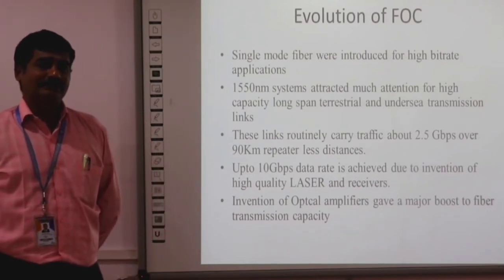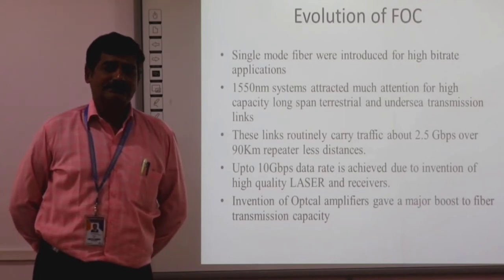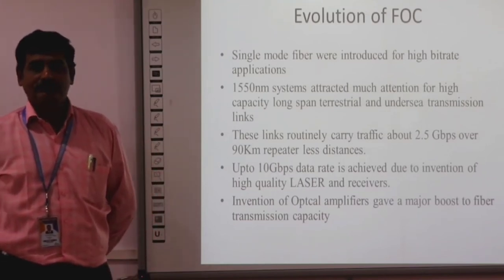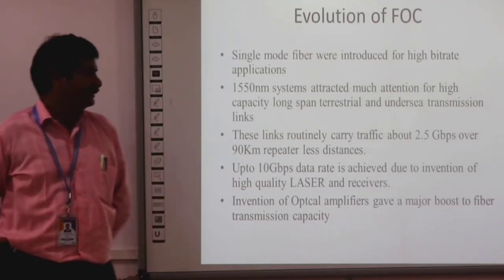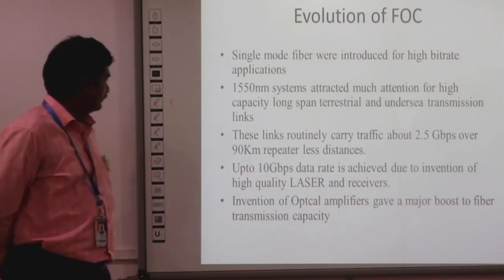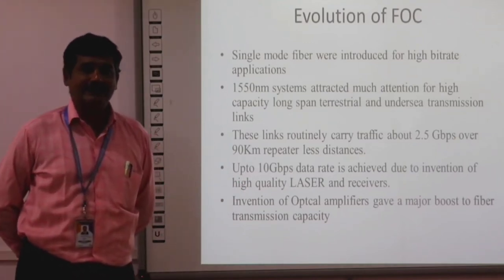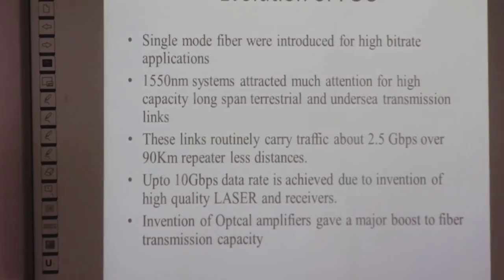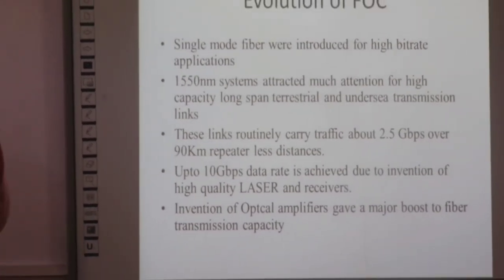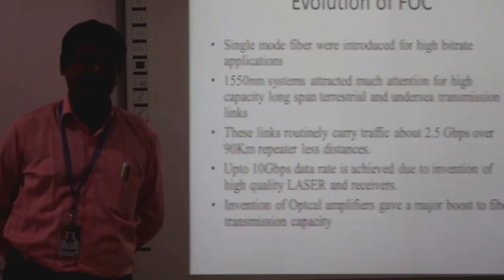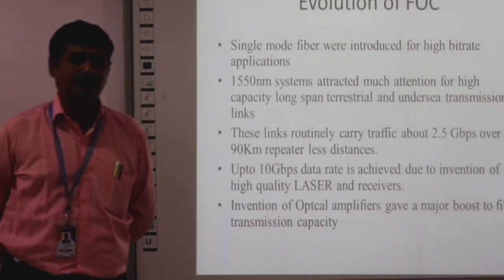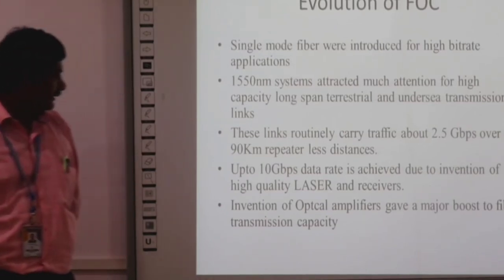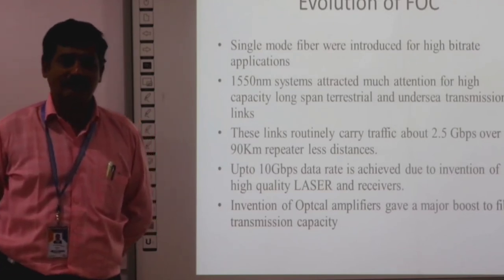The bandwidth of multi-mode fiber is somewhat lesser than single mode fiber. The data rate is very high for single mode fiber, nearly 10 Gbps, compared to multi-mode fiber. Especially for long distance communication, the 1550 nanometer system, that is the third optical window, is used for transmission of signals from one end to another. Another important component is the optical amplifier.